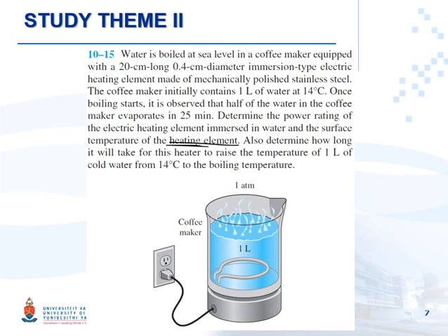After that, you check if that temperature satisfies the condition of nucleate boiling, which means delta T excess between 5 and 30. Then your first assumption was right. If it was lower, you go one back to natural. If it was higher, you go one up. So don't panic. First assume something, and after that try to see if your assumption is right or wrong.